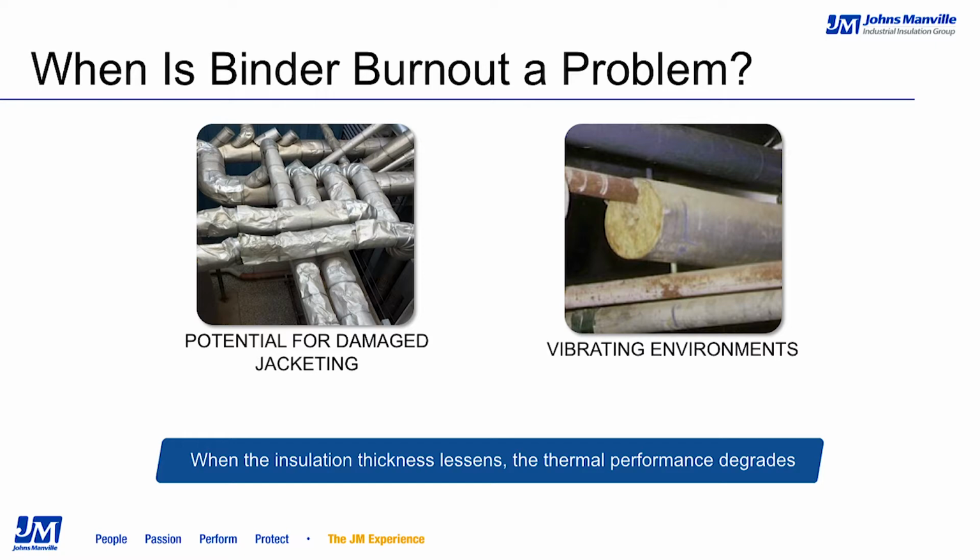The picture on the right shows what happens when binder burnout occurs in a vibrating environment. The product has fallen, and you would never know because you wouldn't be able to see it. Again, personnel safety could be a consequence, and the pipe would not be insulated as needed for your process control.